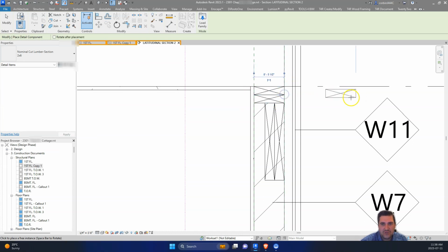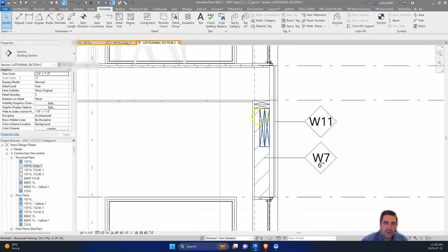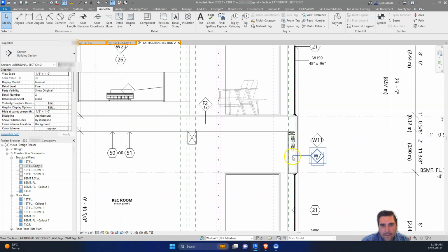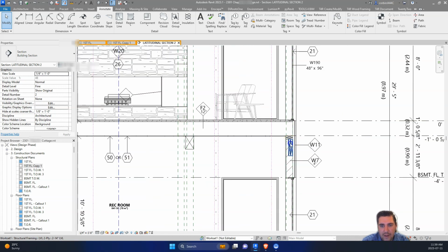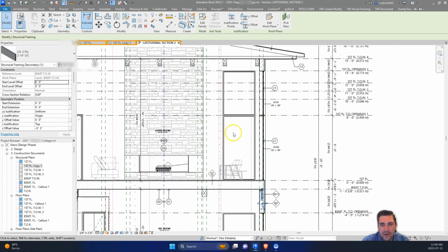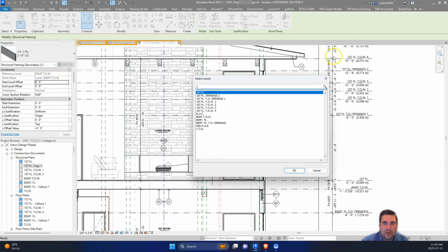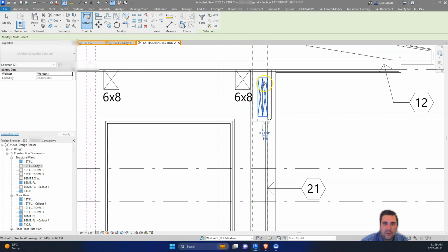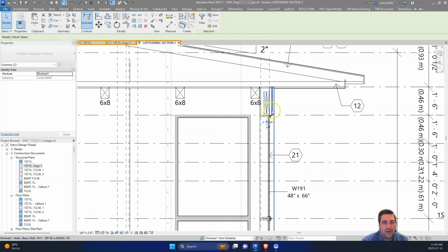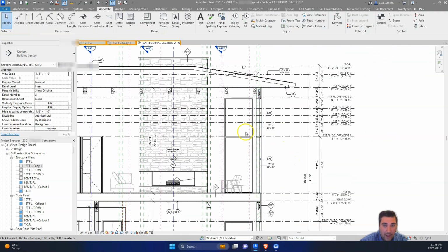And then for simplicity's sake, since I'm here right now, let's paste this up to our first floor top of wall 4 so that we have our lintel up there. We'll still need to size it, but at least it's up there for us to size later. Same lintel is probably going to be fine for up there. And then you can see our big beam here. So that's sizing lintels.